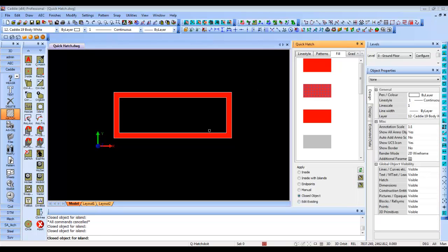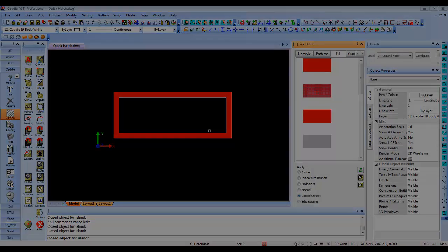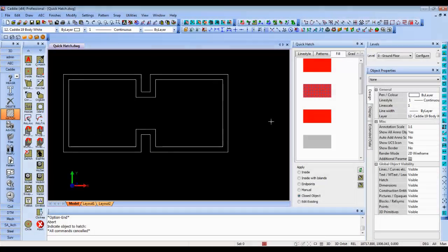I've used a basic shape to demonstrate the hatch. Let's look at a more involved area to hatch. Remember the previous hatch we used was a fill, but now I want to use brick on plan. Using the previous method, I would go and parameter set or get and first set it up before I could insert the hatch. By using the new Quick Hatch feature, I have the advantage now that I can visually confirm using the correct hatch pattern during my process of implementation, which in turn will cut down on my time for editing.